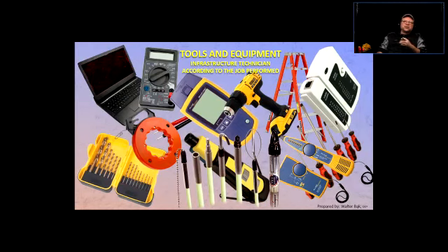The reason for that is you don't know the chemical consistency of that soap, and you don't know what that is going to do to the jacketing of the wire, because the jacketing is PVC plastic based. It might not happen right away, but once you put that lubricant there, it stays there, right? And sometimes it's going to dry out and sometimes it won't. But if you put in the wrong thing, you're going to make it stay there.